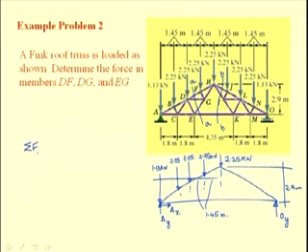If we use the equation sigma Fx equal to 0, this results in Ax being 0, because all the applied loads are vertical in nature and we do not have a horizontal load. So, the horizontal reaction also vanishes. So, Ax is 0.